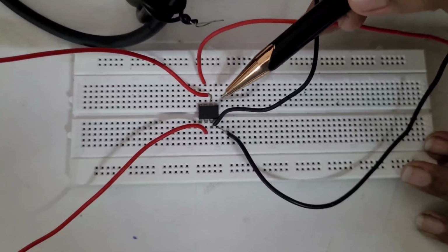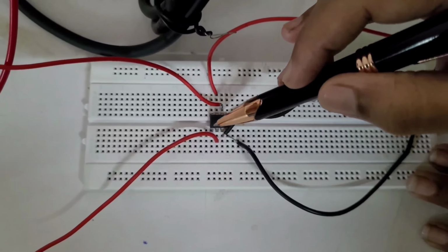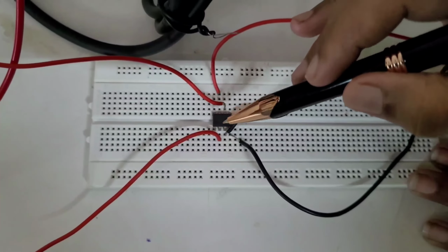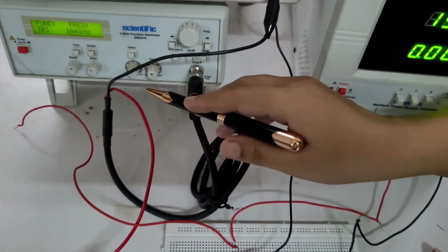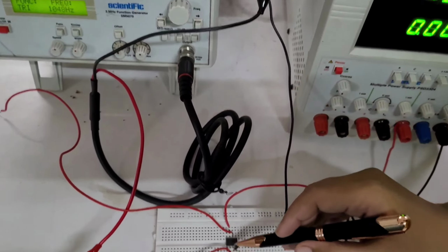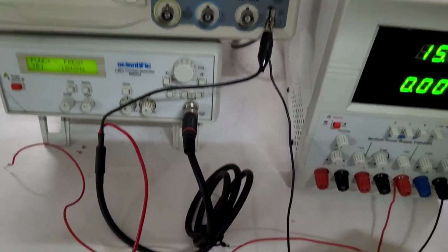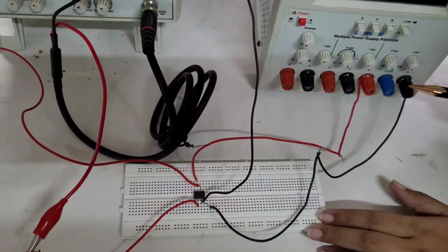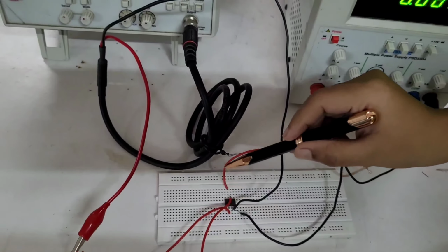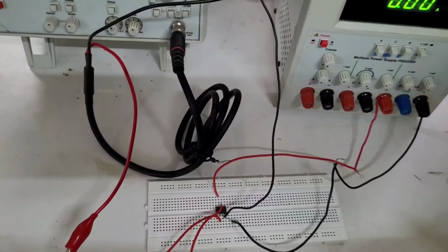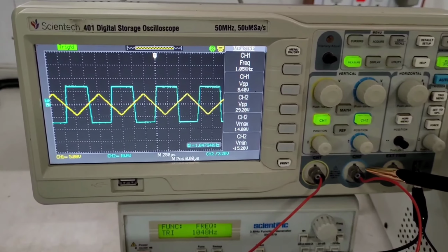This is the Opamp IC. The IC having dot here. From here, the pin number 1 will start. So 1 and 2, second pin, we are giving it with input signal, which is from function generator. Pin number 3 is grounded. Pin number 4, we are giving minus Vsat. Pin number 6 is our output. And pin number 7 is the plus Vsat. Input is given to channel 1 and output is given to channel 2.